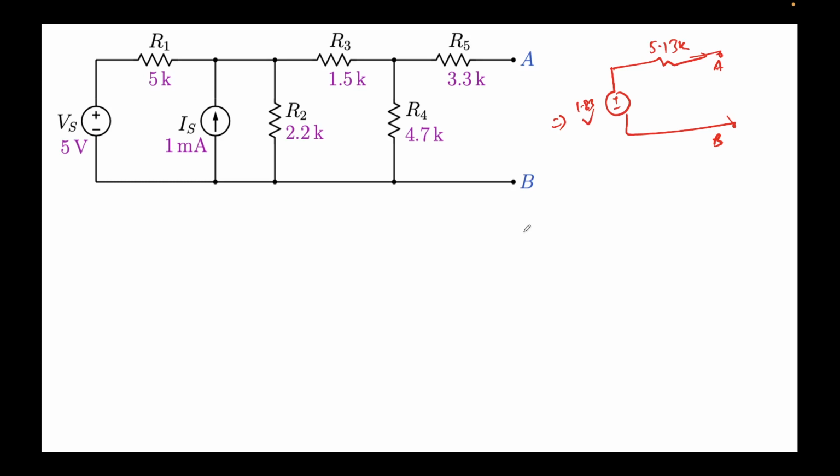Okay. So we had done that. Now we are required to find the maximum power delivered to a load. So let's assume there's a load connected here. It's asking what is the maximum power that can be delivered to a load. Can anyone tell me when maximum power is delivered to a load? Load resistance is equal to Thevenin resistance. Yes, Thevenin resistance, so when RL equal to RTH.